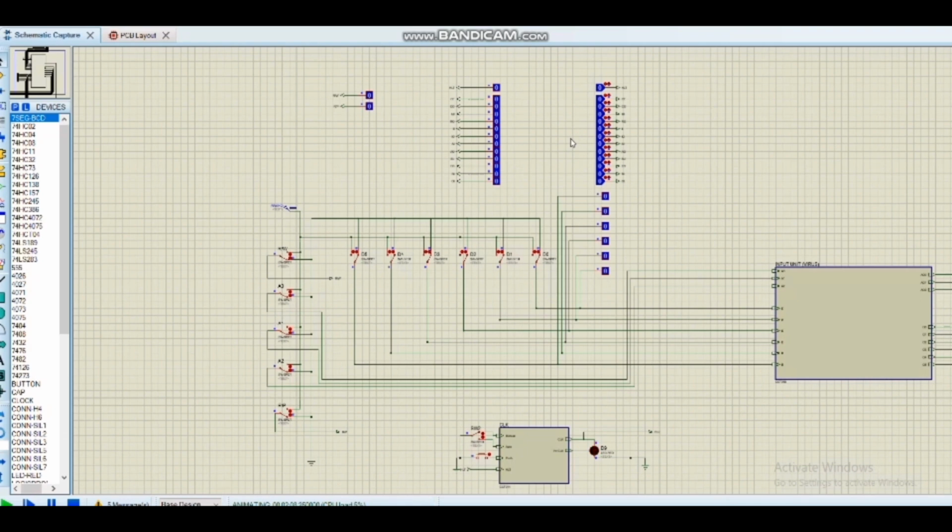These first three locations hold the instructions of what we are doing. So in our RAM we have a total of 6 input bits, so we will divide them: the first three will indicate what instruction we have to follow, and the second 3 bits will determine from where we need to extract our values. So let's say for the first instruction we have to load whatever value is stored in our RAM location 7.